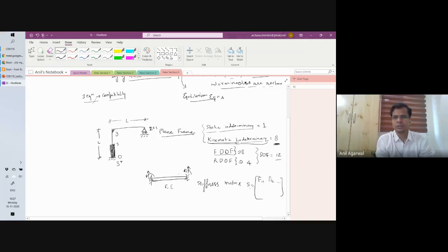So what was the assumption there? The assumption was that EI is constant through the length of the member, right? And the member was a straight member. So as long as these two things are true, and we didn't have any hinges or anything, that is also already incorporated in EI being constant or uniform. Okay. So as long as we have these things true, we don't have to take another kinematic indeterminacy or degree of freedom in that number. Okay. But if you want to, you can always.